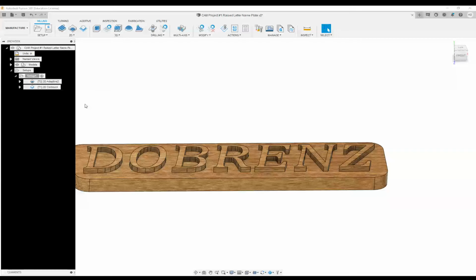And this video is going to show you, once you have all that done, how do you get this to actually spit out your G code? Well, what we need to do is what's called a post process, where we essentially tell Fusion the parameters of the CNC machine that we're going to be using so it can customize the G code for that machine. So that means you actually need to have the post parameters from your machine to make this work.